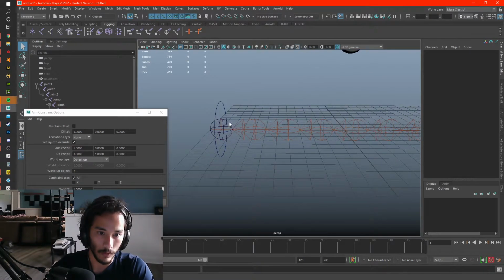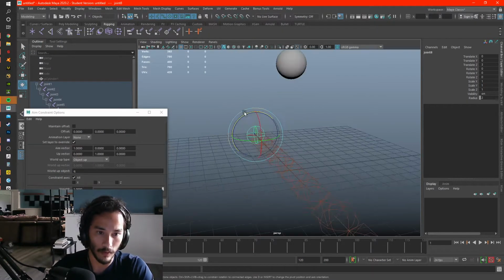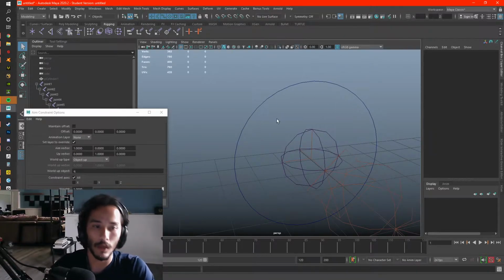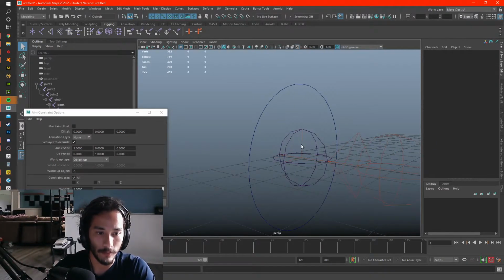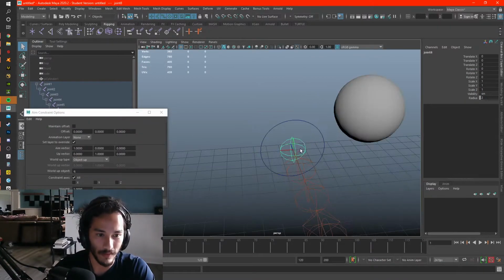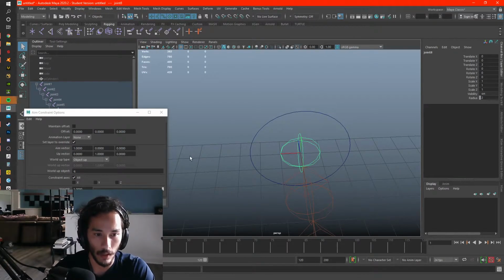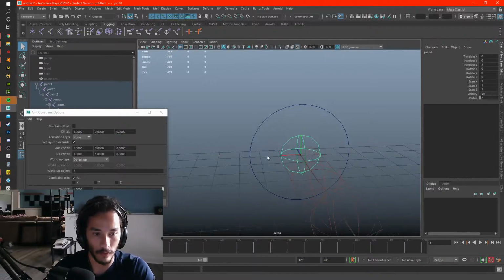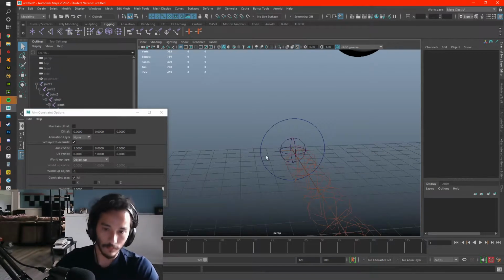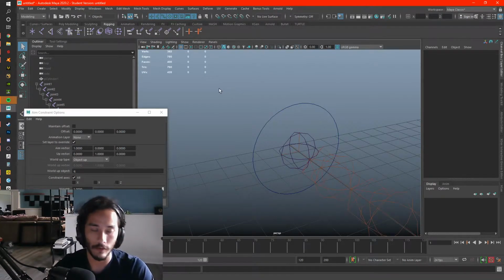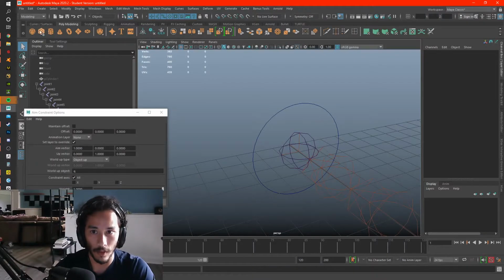So I guess I'll show that with this joint, because that will make life easier. It's the last joint. We need to make an object for this to point towards, and then we need to make another object either directly above it or to its left, so it's constantly facing that object too, so it stays upright. Again, for the aim axis, we can use either a curve or geometry, another kind of polygon.